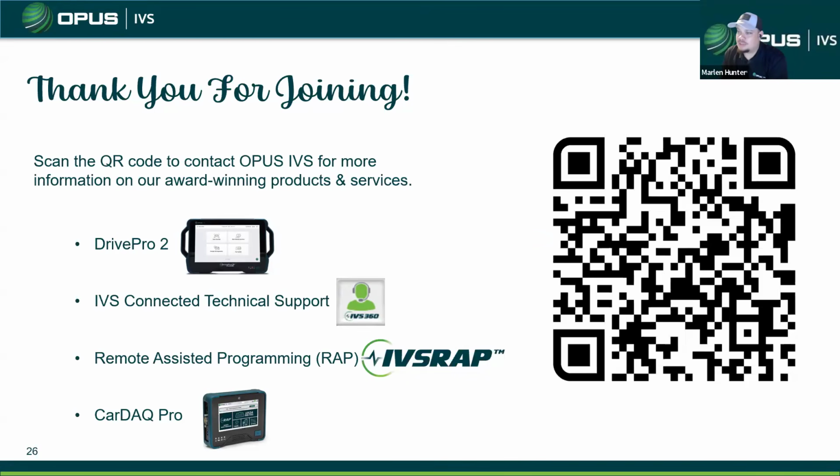And so Jacob, let's see, I missed the first part of the presentation. So as far as ECU Security Key, that'll only have to be done on a new module. Like let's say a new front camera, for an example. That's a one-time module programming setup. Once you put it in, run the security key, it's on there, it's happy. You don't have to do it again. So just anytime it's a new part.